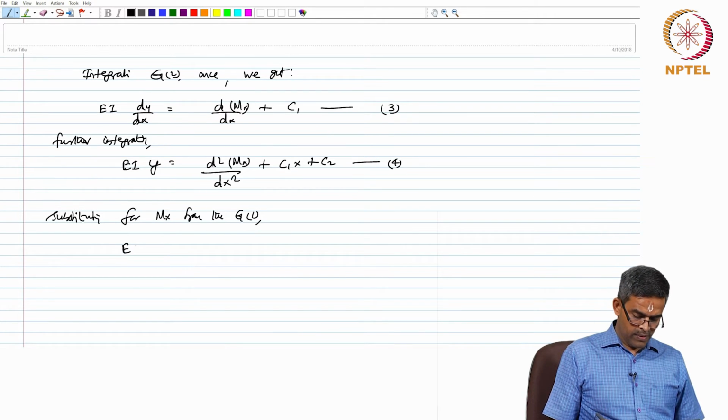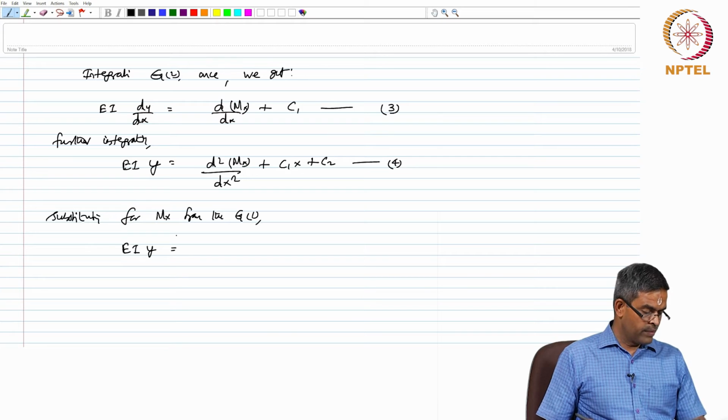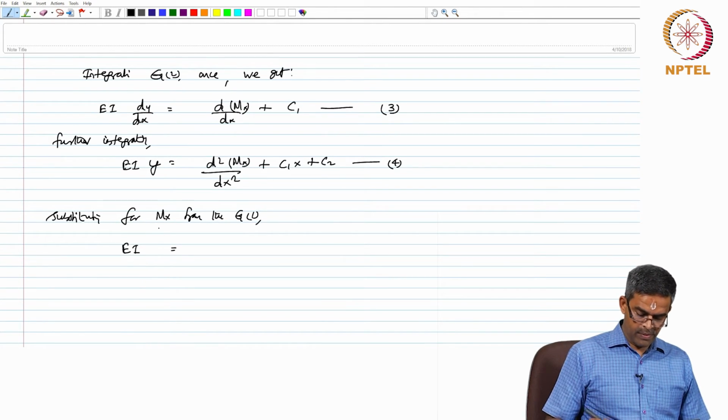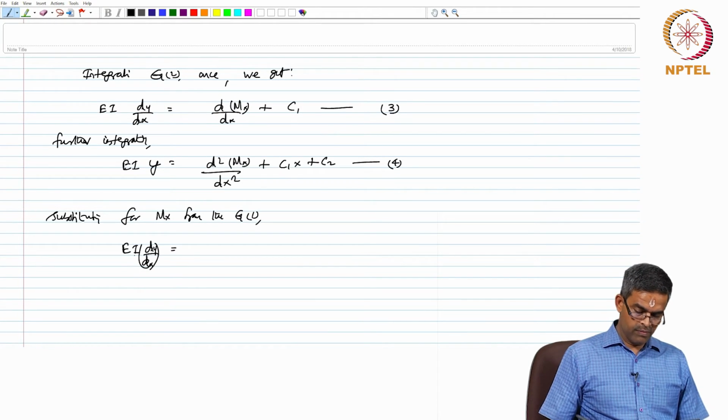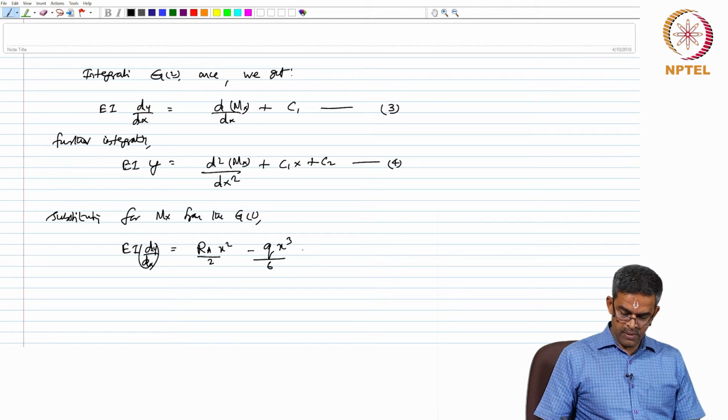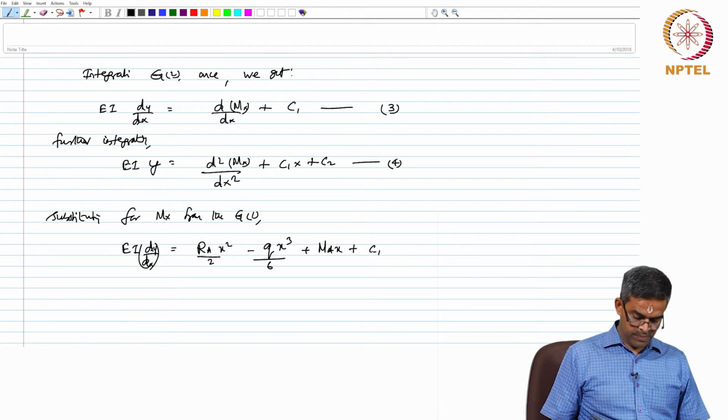So, EI dy by dx will be equal to Ra x squared by 2 minus q x cube by 6 plus Ma x plus C1.